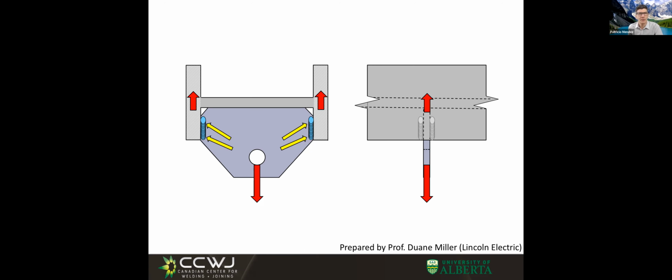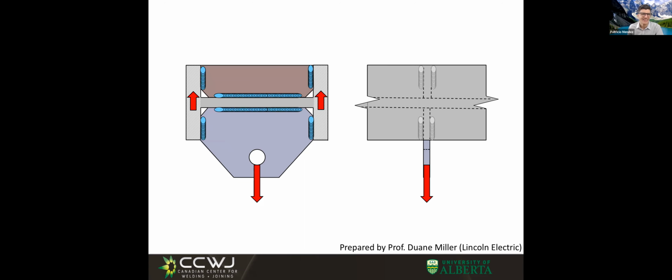What would be a possible solution for this? The solution would be a reinforcement plate. Now, if I put a reinforcement plate on the other side, all of a sudden I made this web, right? Because it's horizontal and we're pulling transverse to the web, that used to be very compliant, now became very stiff. And now we're happy. Now this is a good weld, right? It's very interesting.